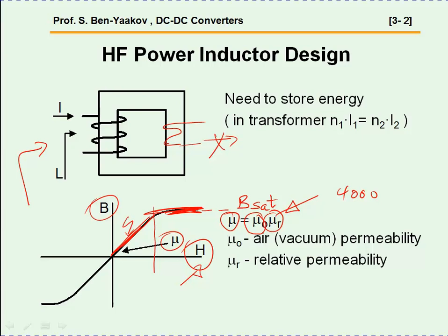In fact, what will happen is that instead of having an inductor, you'll have just a piece of wire wound on a core which is not behaving as a ferromagnetic material. So these are some of the constraints that one has to face when designing a power high-frequency inductor.